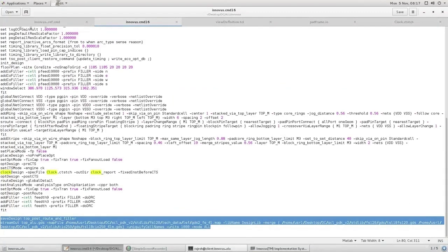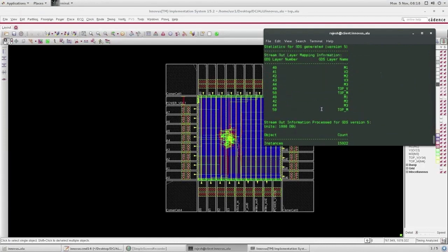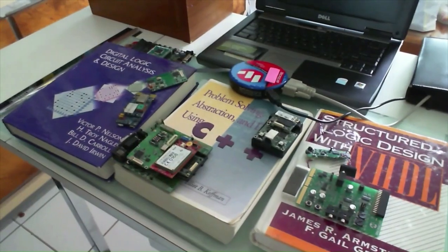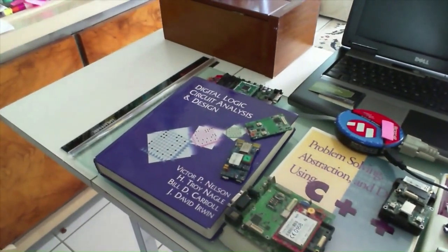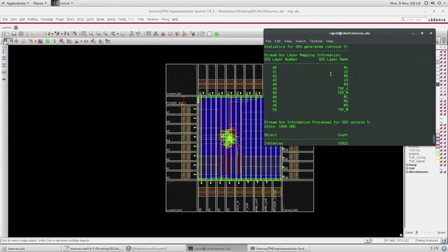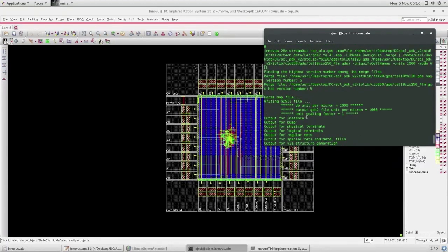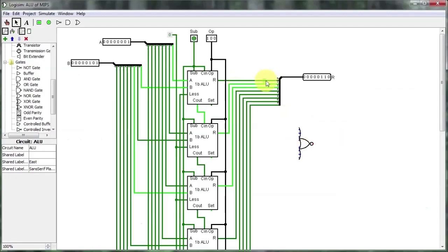Both simulated annealing and quadratic placement accept many controls. They include pre-placement, floor planning, specification of circuits to be placed in adjacent locations, net capacitance, and source to sink resistance constraints, and weights for the various components of the scoring function, including net length, congestion, and population balancing.